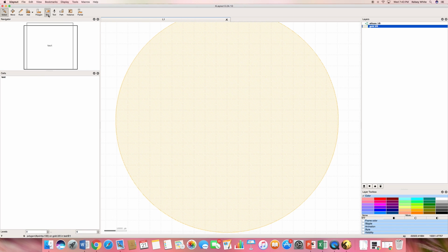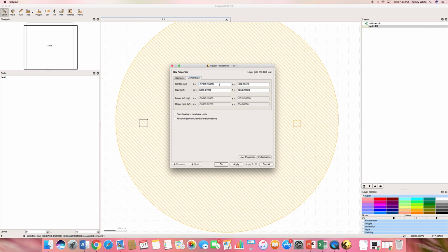And let's say I wanted to put maybe some marks at plus and minus 40 millimeters. So I'm going to just draw some objects. These could be anything. But again, what I'm going to do is center it. I want it to be along the y-axis. Maybe it'll have dimensions of 3 millimeters by 3 millimeters.